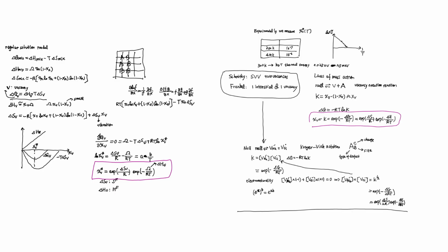So it's going to look like: we have A, we have B, we have C, with the symbol, the superscript and the subscript, so three components for each defect. The A stands for what kind of defect we have. It's a vacancy, with capital V, because there's nothing there, so that's why we're writing a vacancy. C would be the charge, and B would be the site.